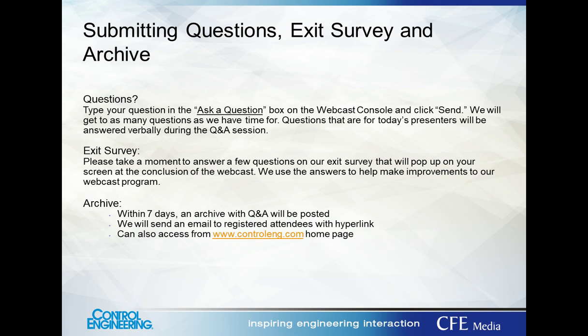The second objective is, if it's got any leftover MV availability, and it almost always has some, it needs to move that operating point in an optimal direction. That's what we mean by optimization in APC: how do we utilize remaining MV availability or degrees of freedom?